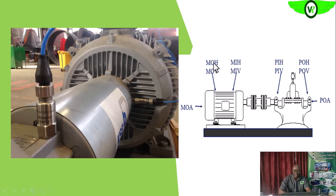So we also have the other two directions. The horizontal direction is this direction that you are seeing here, where you have this probe. This is the horizontal direction to the bearing, and then we have the vertical direction. That is the orientation of this particular probe as you are seeing it. It is placed on the vertical axis to this bearing that you are looking at.